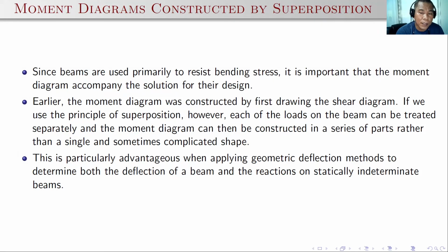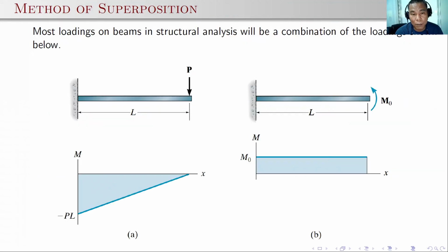But it's easier if we treat it separately, meaning every load should be treated separately, and it will give us a simple construction of the moment diagram. This is particularly advantageous when applying geometric deflection methods to determine both the deflection of a beam and the reactions on statically indeterminate beams. Of course, we will be applying this in the other topics that we have.